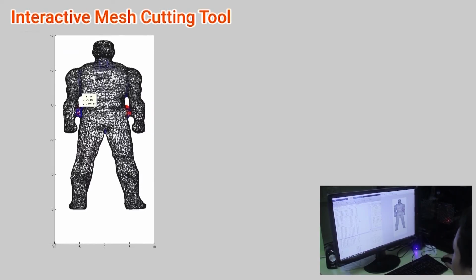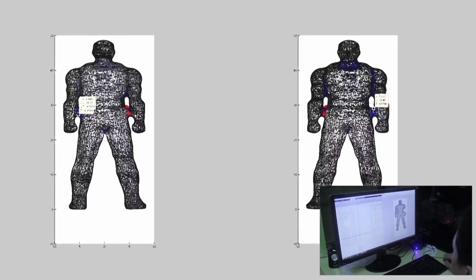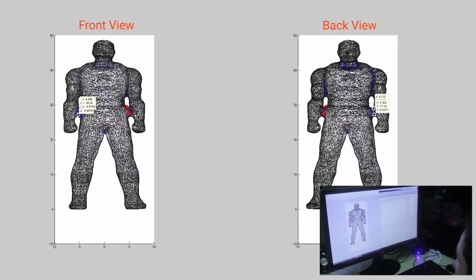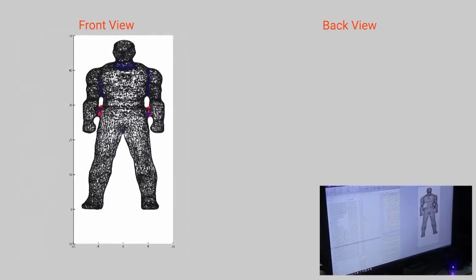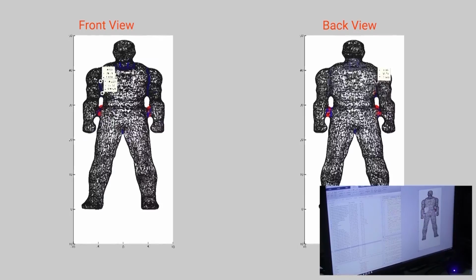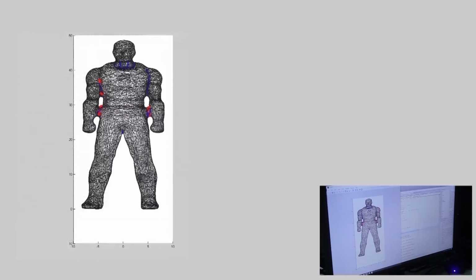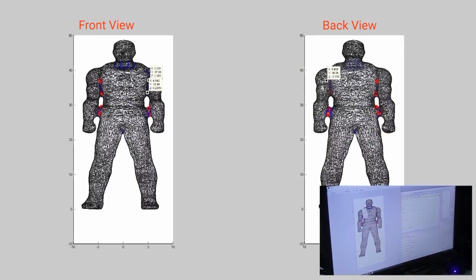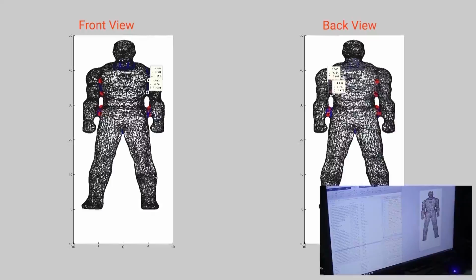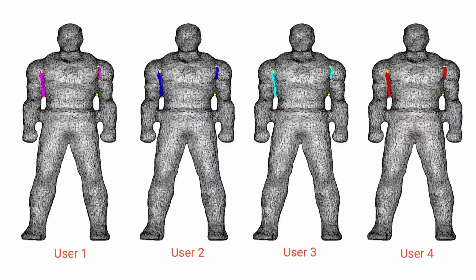The click-based cutting system allows the user to fully cut or slice the mesh. The user is initially presented with a triangle character mesh that contains conjoined body parts. On top of the mesh are candidate points providing suggestions based on the mesh concavity. Afterwards, the system asks the user the type of cut and the boundaries where the cut is intended. The cutting contour is inferred from a feature-sensitive metric given several points of intersection.